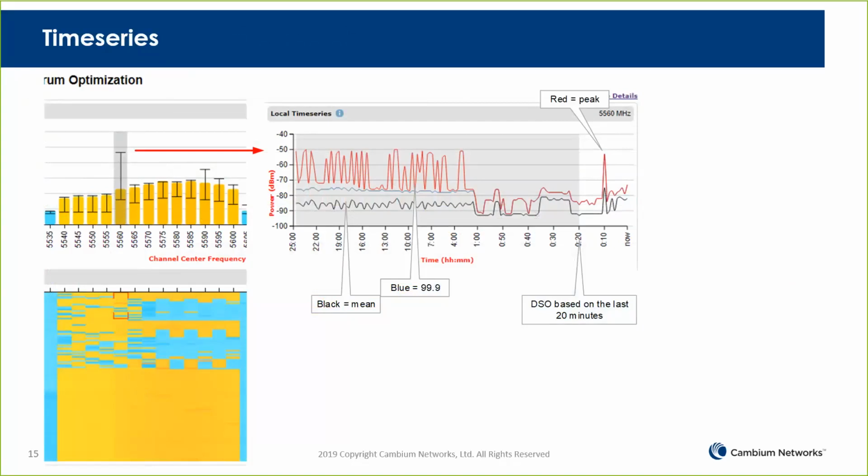If you look on the right of the display at about 10 minutes ago, we have a peak at about minus 53 dBm, a single peak. And that corresponds to the top of the I-beam on the spectrum display. That's the sample that has set the I-beam, and here it is. You can see the point in time where it occurred. Now, I don't know what this interferer is, but for some reason it lights us up periodically with quite a big signal.